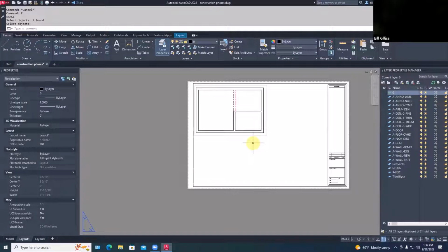The next way, I forget how long this was, 15 or 20 years, they came up with the idea of an annotative text, also in model space. But that is a text style that is aware of the scale of the view that it's in. And if the scale changes on the plot sheet, then the text adjusts its height to remain the same plotted height. The last one, which is what I've started using, fixed height text and dimensions, all 1/8 of an inch tall, all in paperspace. Because then I just have one text height for everything, which is to say one text style. Notes, dimensions, regardless of the scale of the drawing.